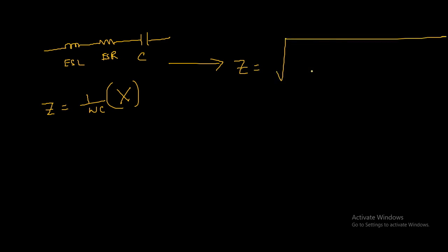In that case, Z is equal to the square root of ESR squared plus (XL minus XC) whole squared. All three components, the ESR, the capacitive reactance XC and the inductive reactance XL, are frequency dependent.